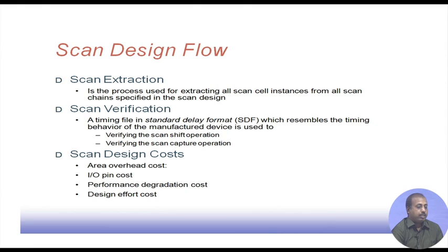Then there comes the scan verification. A timing file in standard delay format, which resembles the timing behavior of the manufactured device, is used to verify the scan shift operation and scan capture operation, whether those two operation delays are coming in proper timing or not. So this standard delay format file will have this timing information.